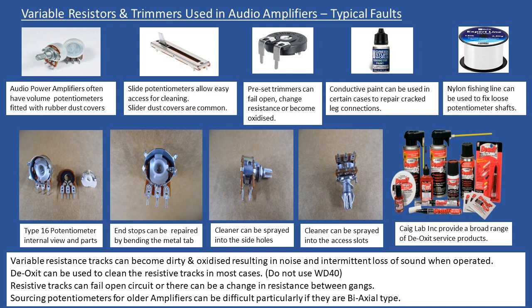Because if it's carbon based, what will happen is it will start to dissolve the hydrocarbon that it's made out of. So you spray it in there, you work it around, you say, oh, it's going to clean it, and then after a few minutes it's like, what just happened? Well, what just happened was the carbon track of the potentiometer just got damaged because of the WD-40, right?